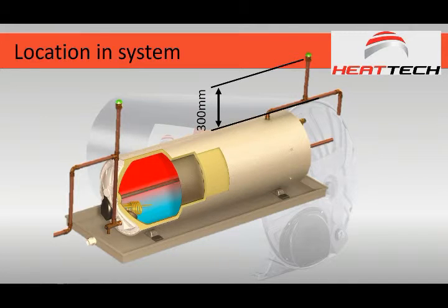And that's important to notice: the start to open pressure, that 3 kPa, is a very, very low pressure. It can take fine tuning to make it actually work at that pressure without failing. And I think that's where the risks come in. Technically, I believe it's quite possible to design something that will withstand all pressures up to 600 kPa or even higher, and still work well. But it's not a guarantee that all designs will work like that.